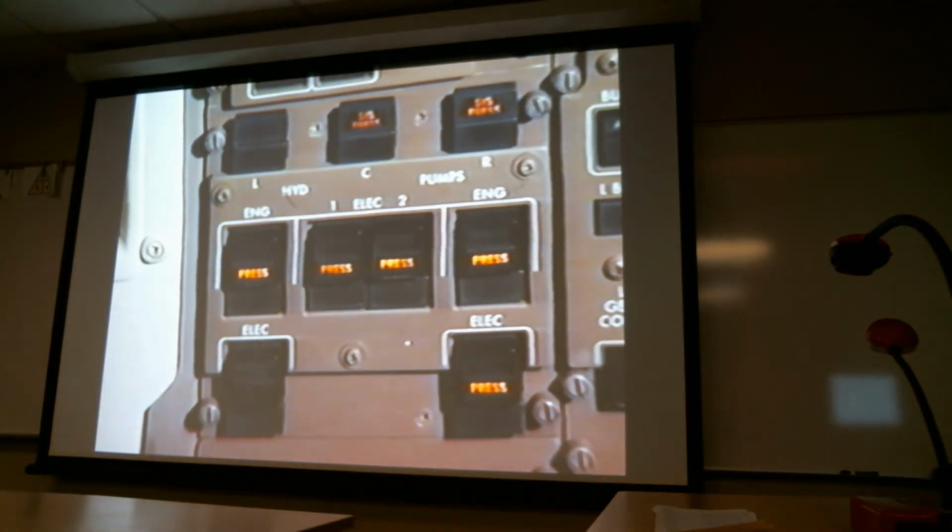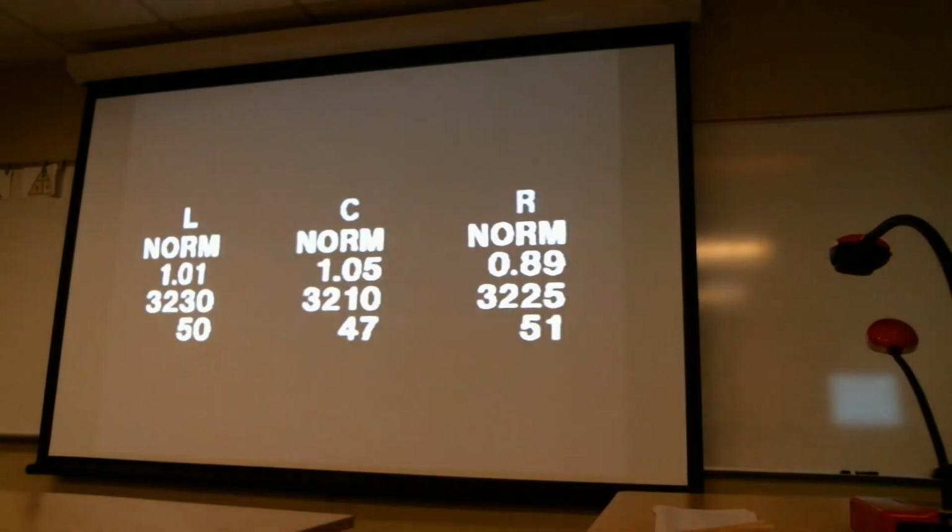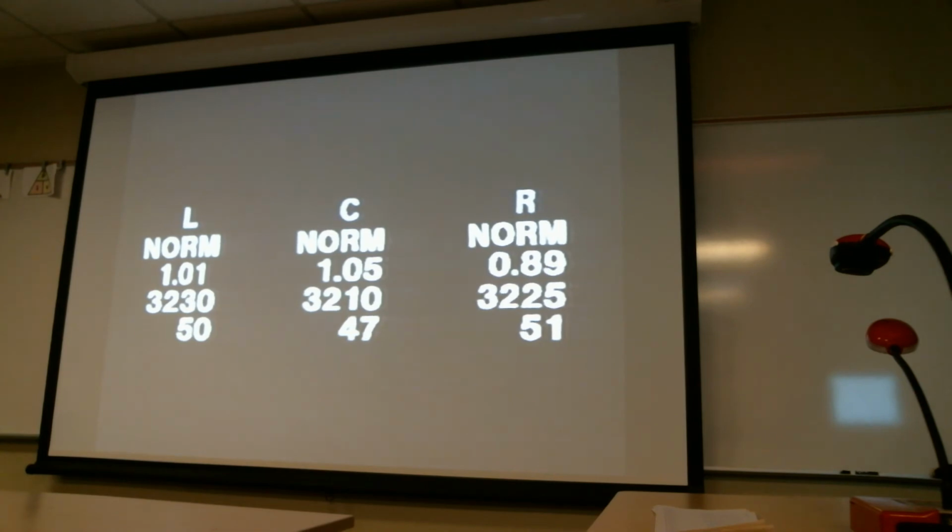With the landing gear doors closed, shut down the ACMP. Check the fluid levels on the electric hydraulic page of ICAS. If the levels are within the previously stated limits and all maintenance has been completed, return the aircraft to normal.